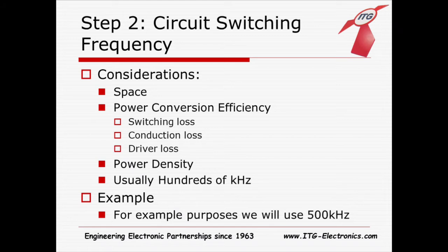Step two is determining the circuit switching frequency. There are many things to consider when determining the switching frequency, such as space, which is going to drive how high or low you're going to be able to tolerate having the switching frequency, because the higher the switching frequency, the smaller the space, which is a plus. But higher switching frequency also drives up switching loss and driver loss, which is going to affect your power conversion efficiency. And then power density.